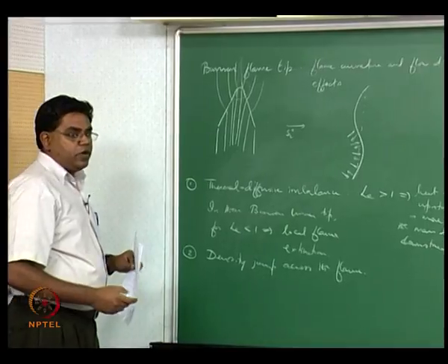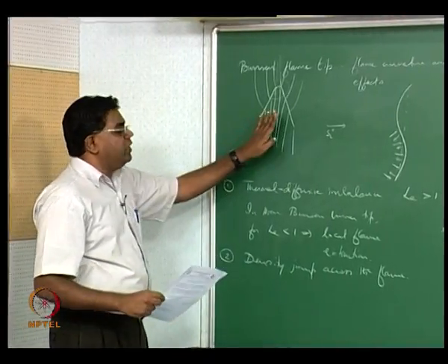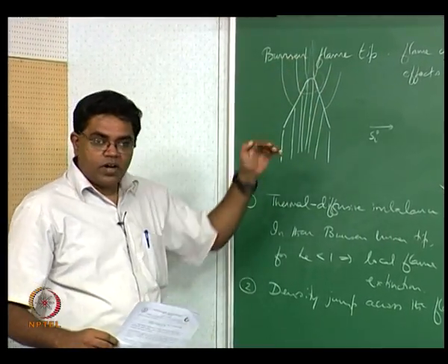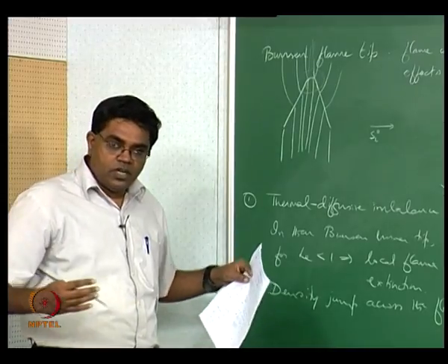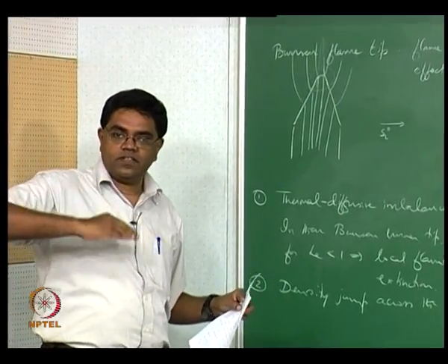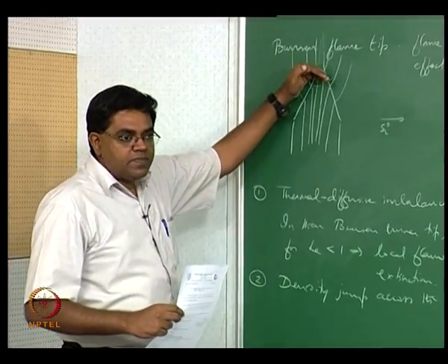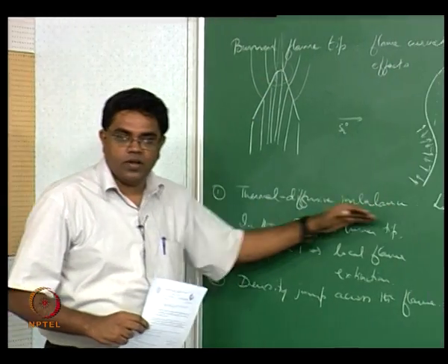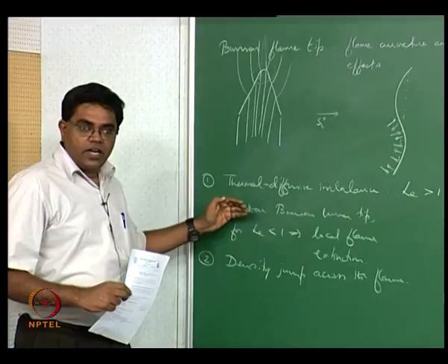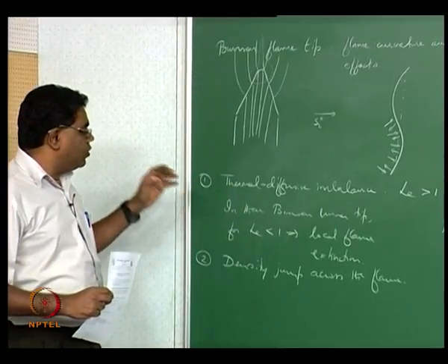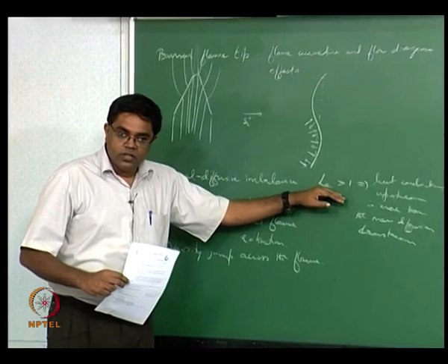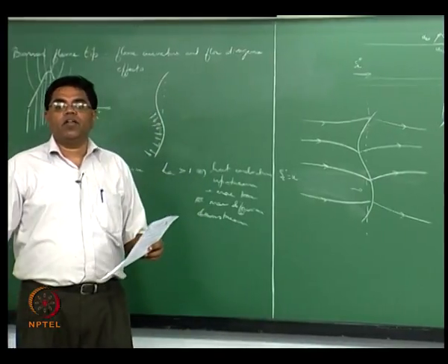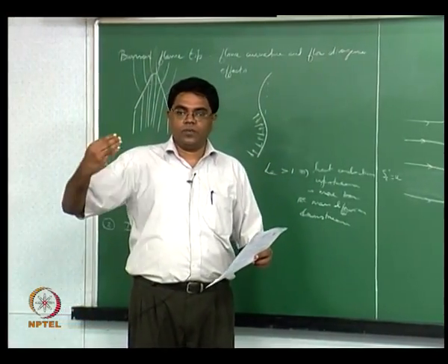Put another way, the flow speed is greater than the unstretched flame speed, and at the tip, because you now have a concave curvature, the flow tends to converge and flow faster. That means the flame speed has to increase much more to counter that, and that would be through the thermal diffusive imbalance. That is obviously possible mainly when you have a Lewis number greater than 1, but still, since this effect is countering that, even when you have a Lewis number greater than 1, you could have conditions of local extinction.